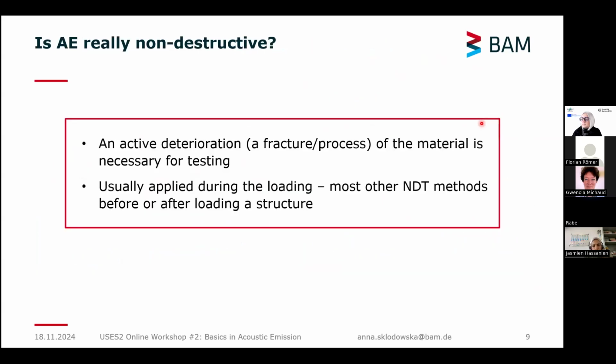So this raises a question: is acoustic emission really non-destructive, since we need some kind of active deterioration, a fracture, a process of the material for the testing? But in general, we don't destroy with the method itself. So in general, this fits into non-destructive testing methods. And acoustic emission is also usually applied during the loading, whereas most of the other NDT methods are applied either before or after loading of the structure.